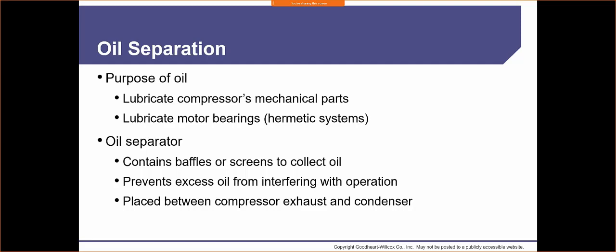So to combat this, the engineers designed what's called a belly band. It's a small little heater that's put onto the base of your compressor that keeps the compressor just nice and toasty enough for that oil to want to stay there and not migrate to other places.